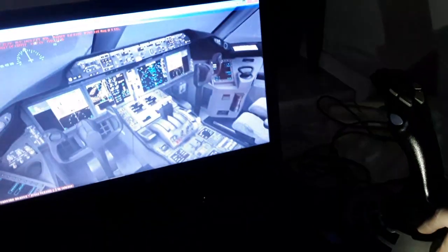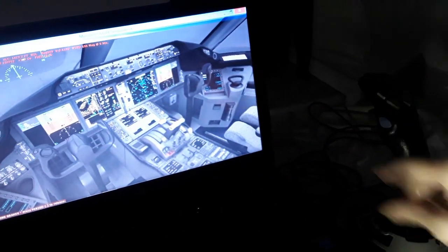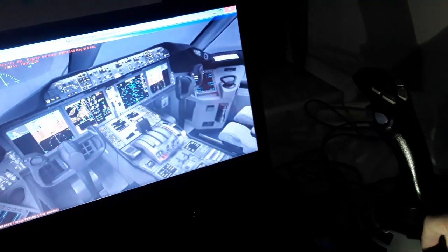I'm going to show you also the thrust levers over here, how I use the thrust levers to increase the thrust commanded from the engines by the FADEC. The FADEC is the full authority digital electronic control computer, one installed per engine gearbox, with dual channel redundancy: one channel is active, and the other takes over if needed. It controls modes and displays all the engine data using the upper and lower EICAS.